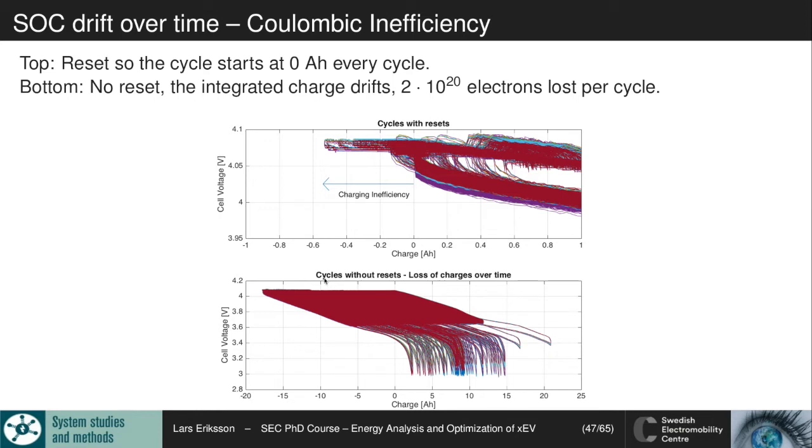So here we just integrated the current into and out and not bothered about making the reset, just integrating. So this is Coulomb counting, gives rise to this. But then with some intelligent means we need to couple it to the voltage also. So this becomes an important part in monitoring the state of charge.